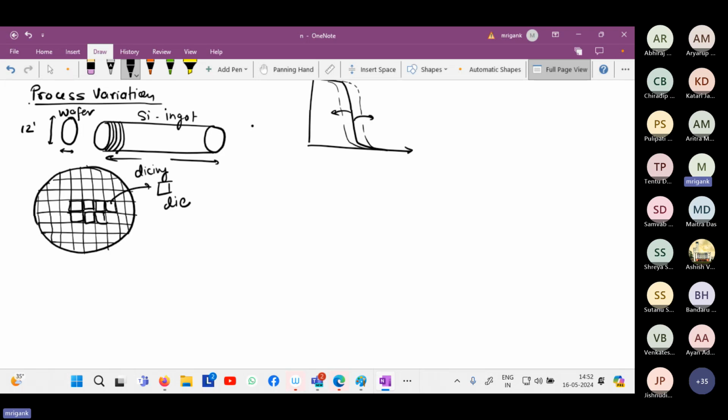For a PMOS transistor, what kind of substrate do we need? What kind of doping do we need in the substrate? So we need elements which have fewer valence electrons than 4, that is, which can produce holes, like boron and aluminum. I said P-type. For NMOS, what kind of substrate do you need? N-type doped or P-type doped? For NMOS, we need a P-type substrate.